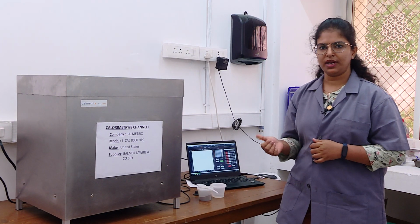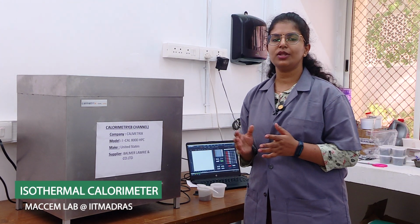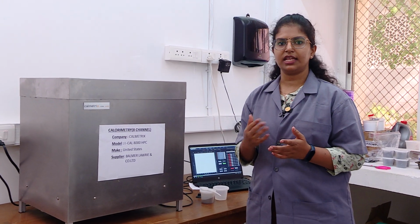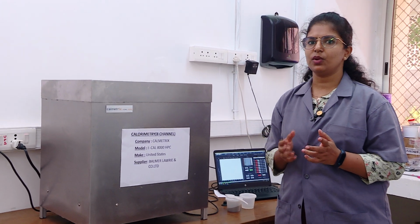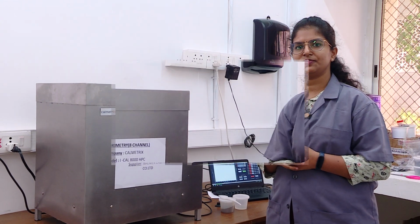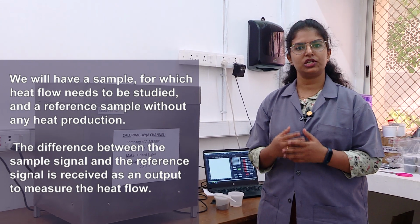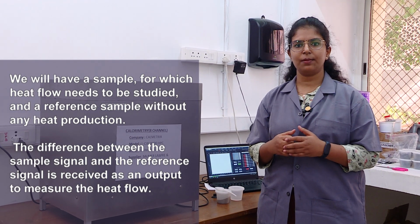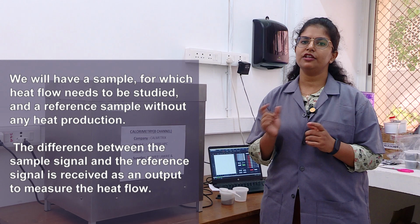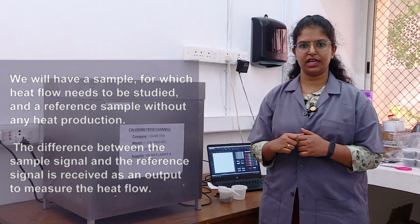Now let us see the equipment, the isothermal calorimeter, which is used to study any reaction or process which involves enthalpy change. Either it can be physical, chemical or biological reactions which involve enthalpy change. In our lab, since we deal with cementitious binders, we use the isothermal calorimeter to measure the heat evolution from cementitious binders. So here we will have a sample and a reference sample. The sample is the one for which we have to measure the heat evolution, and the reference sample will not have any heat production. So the difference between the sample signal and the reference signal will be received as the output to measure the heat evolution.